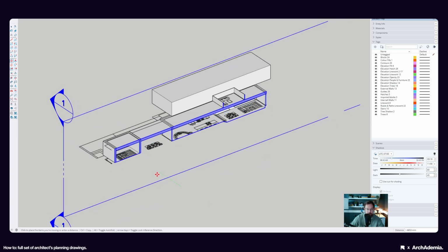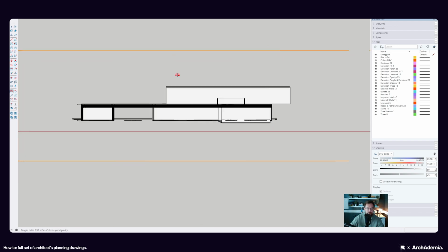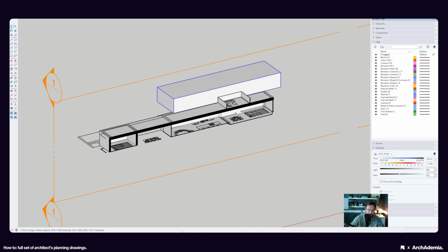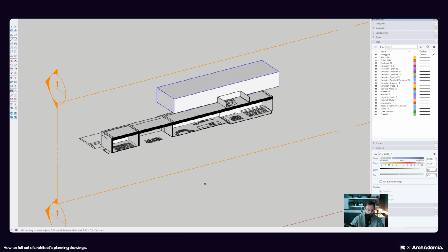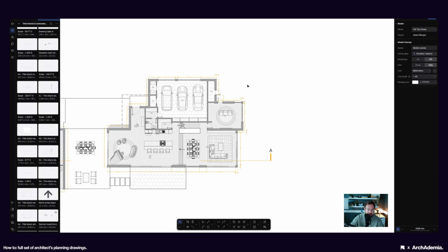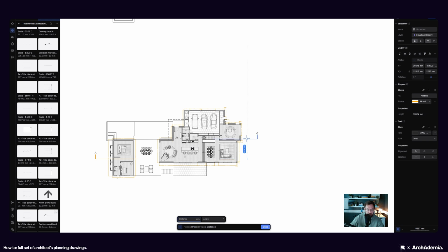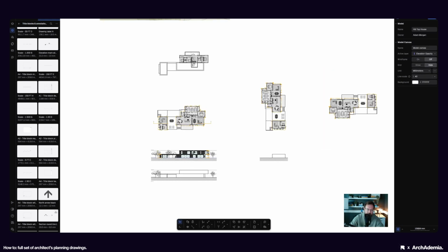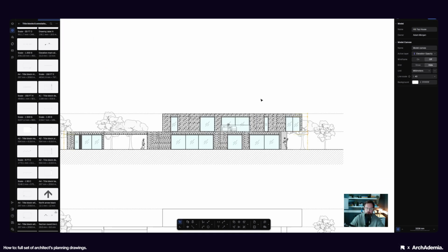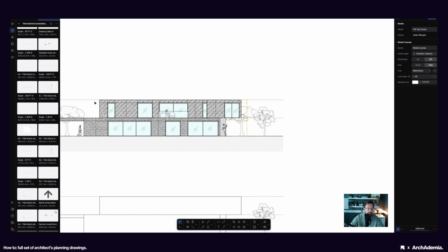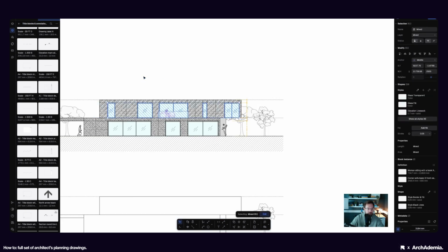Let's do something like that to where we've got it drawn. So we've actually used the 3D model to realize that that top floor would be in elevation. Now you can step sections. So we could move that up like so, and then you would draw a stepped line in between. But I think we're getting a bit fussy there. So we'll just keep to the principle that what's in the elevation will stay in elevation like so.